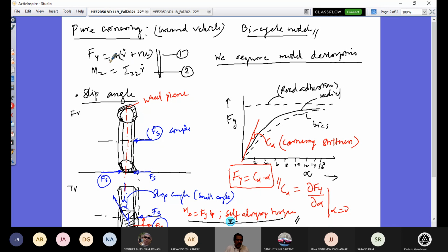With that note, we understood an important physics of slip angle generation at the contact patch, and that is what is responsible for the variation in Fy. So Fy is because of slip angle, and you get your Fy by multiplying slip angle with your tire cornering stiffness. The tire cornering stiffness is defined by the variation of Fy as a function of alpha, by this slope when alpha is equal to 0. And this partial derivative is because I don't consider camber angle simultaneously here, right?